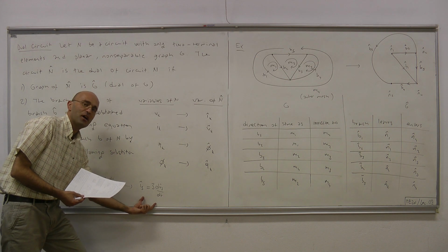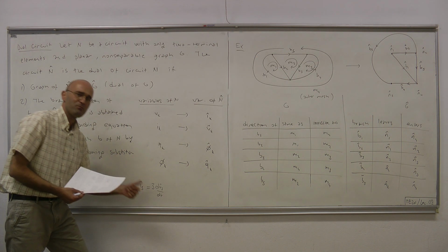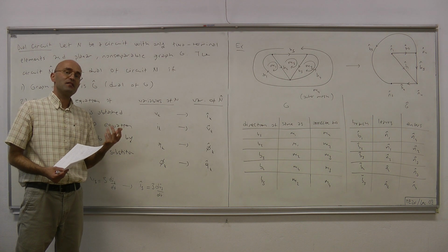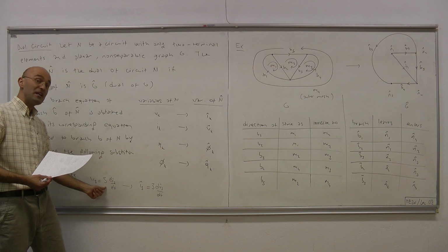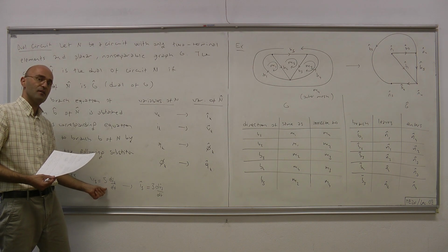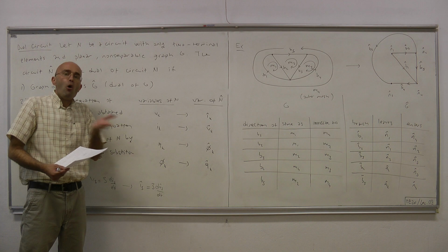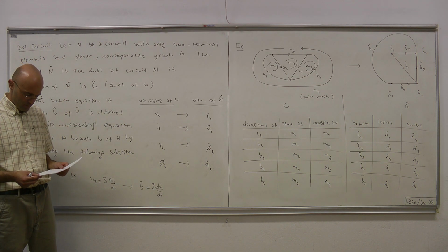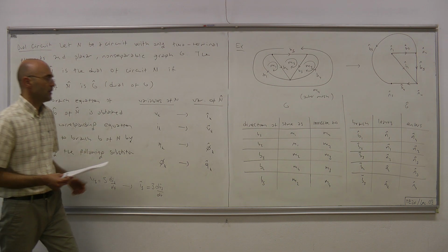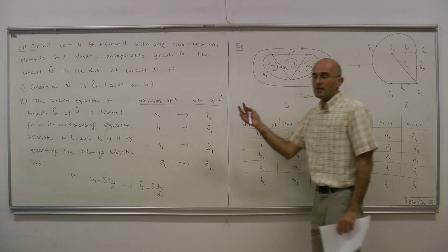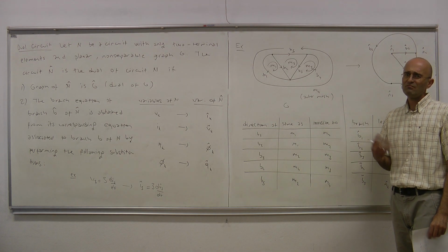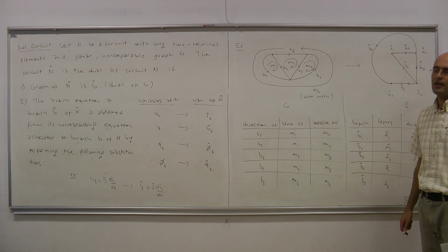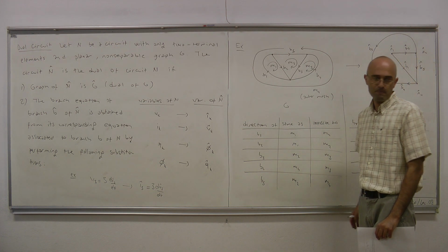Again an LTI resistor, but this time its conductance appears. Here we have 3 ohms that describe that component. That corresponds to 3 mhos in the dual circuit, or 1 over 3 ohms in the dual circuit. Now it's quite straightforward. Now let's apply that procedure to an actual circuit. And for a given actual circuit, let's try to obtain its dual.